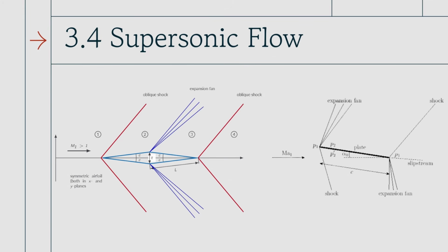And so what you get is the opposite of a shockwave, which we call an expansion fan. There are some pretty cool properties involved with the expansion fan. Essentially, it is continuous. It is a pressure gradient continuity across there, so you can do some really cool thermodynamics in that area. And then, of course, you get a shockwave at the end of your airfoil as well, because your flow is not expanding anymore. So there's a shock there to redirect the flow into a straight line, the way it was traveling before the airfoil.